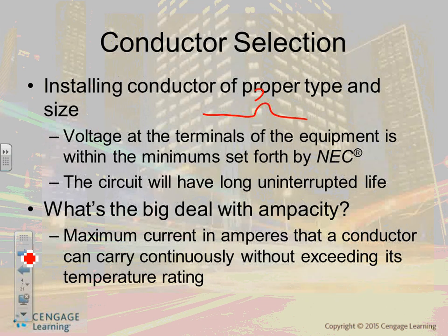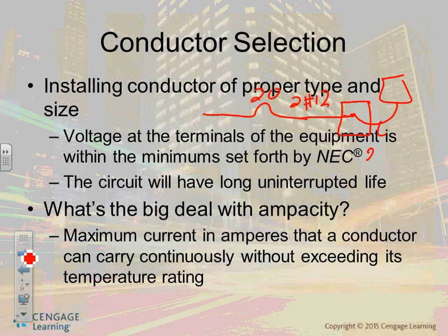He did a 20 amp circuit here, two conductors number 12 into the box. Now inside the box, the fixture whip that goes to the AC was two number 10. And this is your AC, and this is your disconnect, right? So 10, 12. Remember, what controls the circuit? The overcurrent device. As long as the overcurrent device is rated to protect the smallest of the two, you're good to go. That's not a violation.